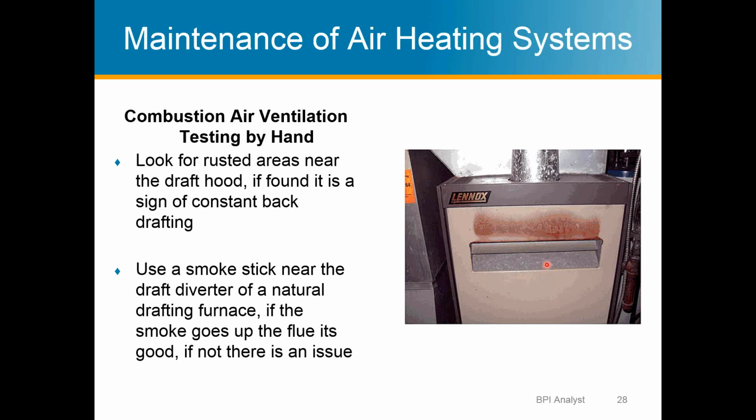So this is a natural draft furnace, and this rust right here, it's not just a bad paint job, but this is from spillage. When the burners light and the heat is coming up through the heat exchanger in here, this is where dilution air is added, and then it goes up the exhaust.